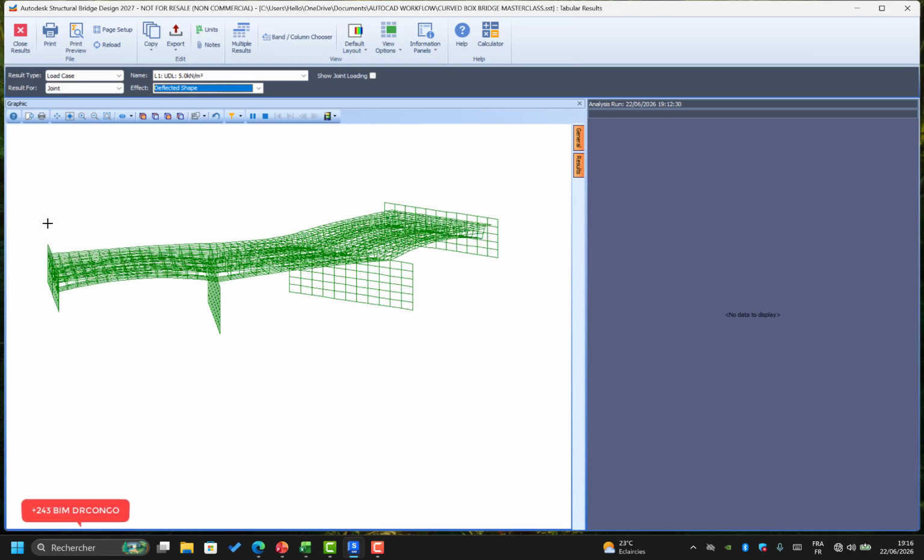You can see here there can be displacement between our abutment and our bridge deck, because there is no support condition about our deck. You must take it into account. I did it by default to show the effect when you neglect some condition. As a structural engineer, we can see what problems and difficulties can occur when we are building your bridge. We must take it into account and see how we can resolve it, fix it and reduce the effect.